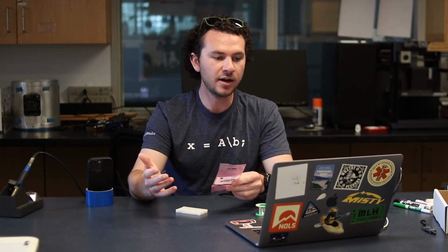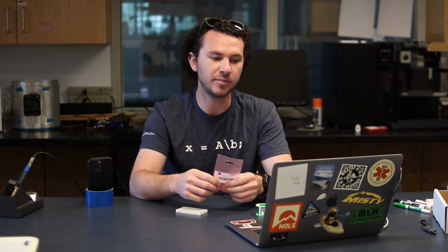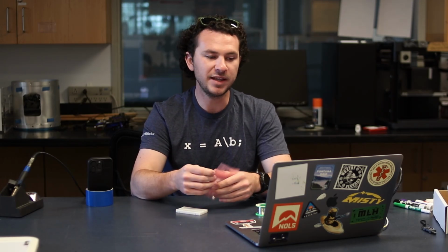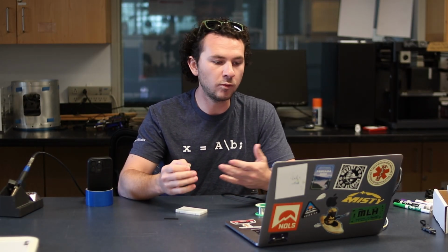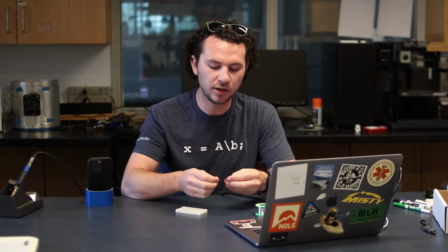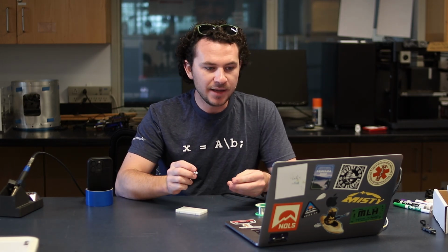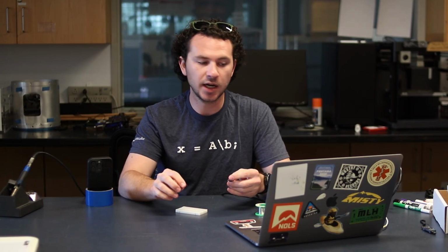Before installing our IMU, we need to solder on some header pins so we can press it into the breadboard. That process should be familiar by now, but we're going to walk through it one more time. In this case, we don't need or want to attach all of these header pins. Our IMU comes with the option to use a few different communication protocols to talk to it, but we plan to use I2C, so we only need to feed it 5-volt power and connect the SCL and SDA pins.